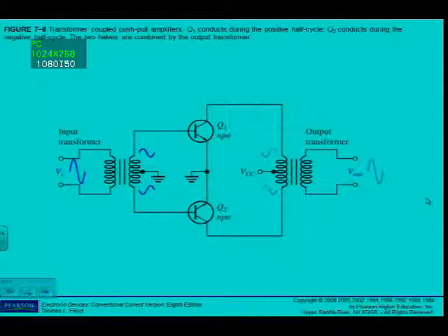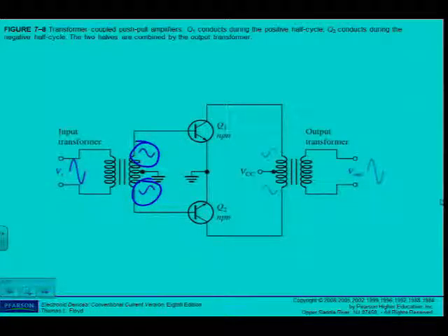you can see the transformers. What type of transformers are used here? You used them in Electronics 1 for full wave rectification. Center tap transformers. Can you see that? Characteristic of a center tap transformer on the secondary side: two waves, 180 degrees out of phase. Same principle that's been used on the full wave rectification.